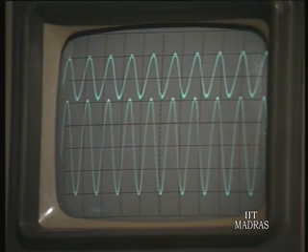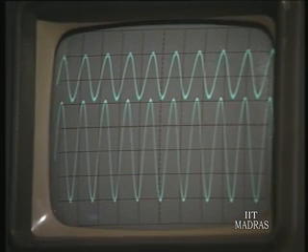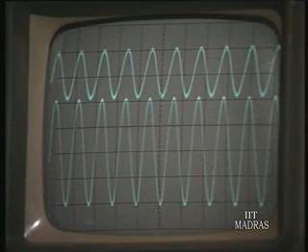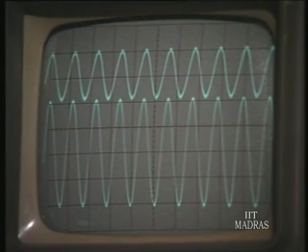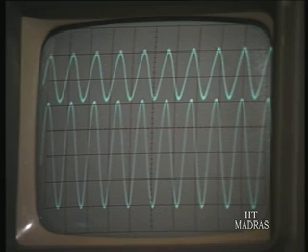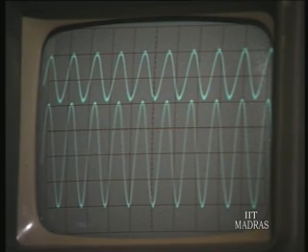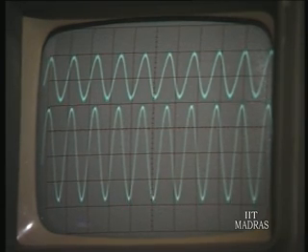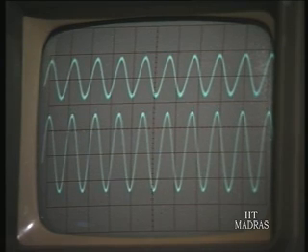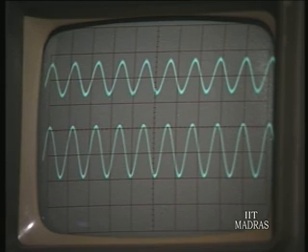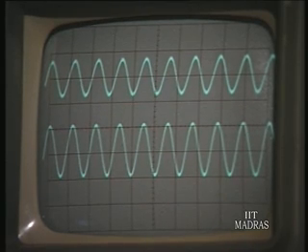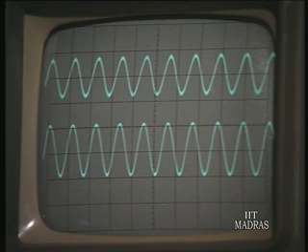Output is 200 millivolts peak to peak or 0.2 volts peak to peak. Input is 20 volts peak to peak, that means 10 volts peak. Now, it is at this value. You can see she is going to almost halve the input, reduce the input. So, she is slowly reducing, you can see. The control thing is coming into action, slowly reduce, and now input is almost half the original value, output has still remained the same, it has not changed.